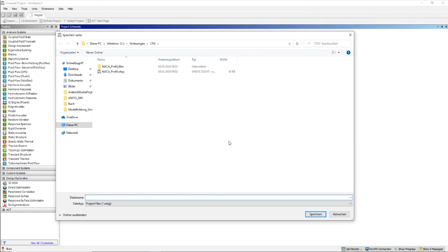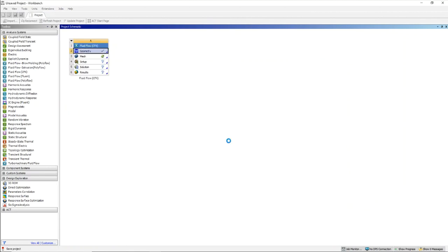And we can choose a name, for example airfoil design number 1, and prevent blanks, prevent German letters, prevent French letters, prevent any special signs even in the path of your model.